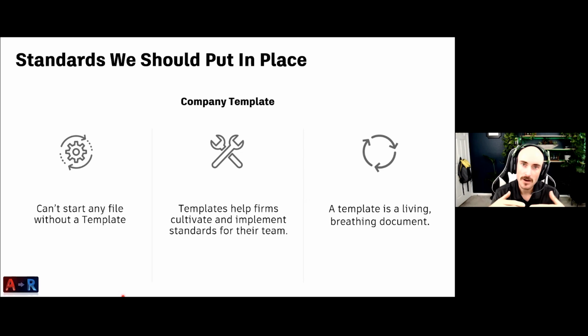Now, as we start out in Revit, when you hit File, New from Template, you have the ability to select your version in terms of discipline. I recommend checking out the other disciplines. They have some great schedules. Or you can just hit structural, that's where you'll start out with, and then start implementing your standards, like what text types do you use? Or maybe dimension styles with whatever arrow leaders you use as well. Going through and setting these and starting your templates.